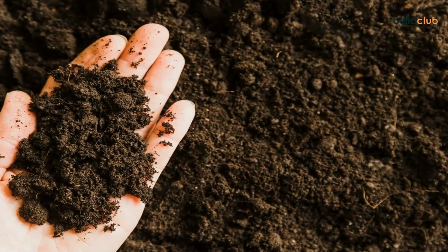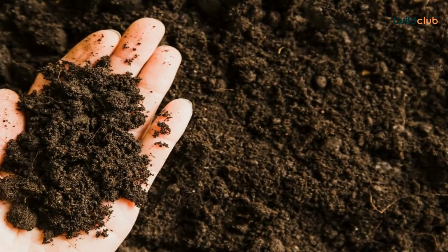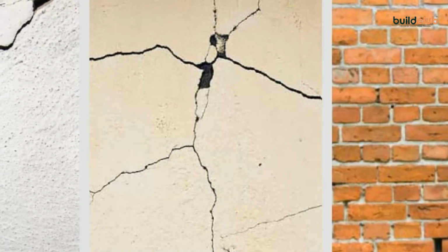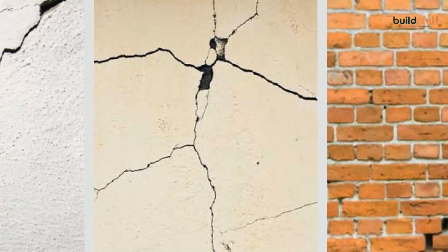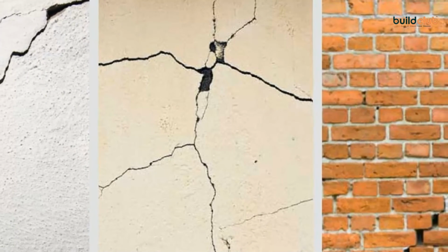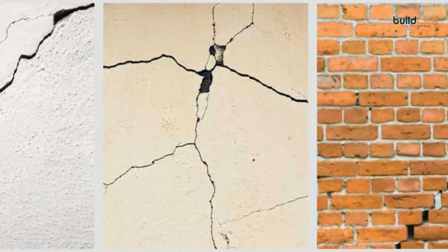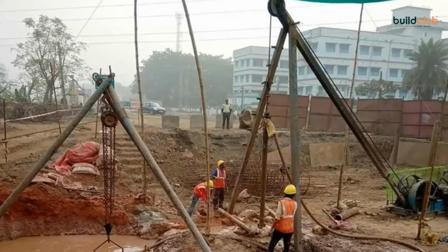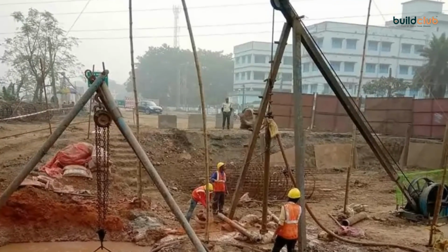Such soil consists of clay or black cotton soil, basically the expansive type, which may lead to serious threats of building consolidation, leading to severe structural cracks and sometimes collapse of the entire building. Beware of such kind of site, never go for standard footing, always opt for friction piles.